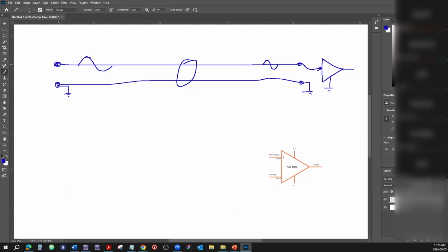Now, microphones, if it's a dynamic microphone, like this one here, it's a passive device, which means we don't plug it into power. The movement of the membrane creates disturbances around the coil and magnetic field and whatnot. It creates an electrical signal, but it's relatively weak compared to active devices. So it would be in the range of maybe 1 millivolt.